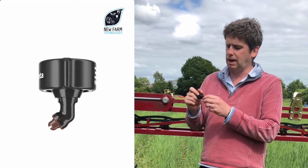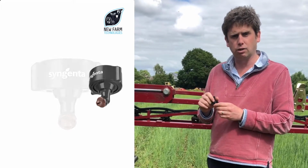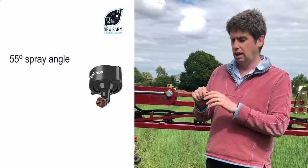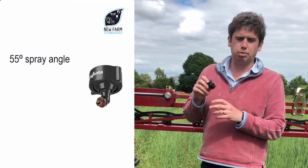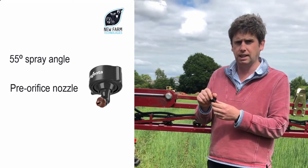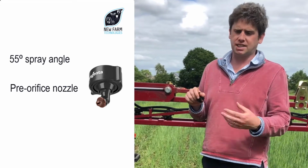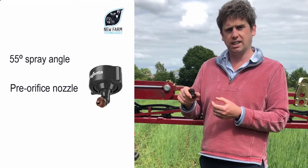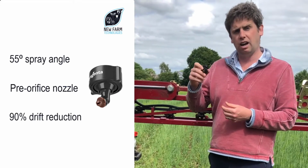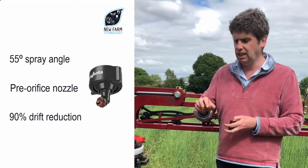And what's key about the 3D90 is several things. A, it's got a 55-degree angle, so that mitigates the clods and shadowing we see. B, it is a pre-orifice nozzle, so it gets its drift reduction capability and is pulse width modulation compatible. And C, which is the most important, is its 90% drift reduction. And that is really important because we can get good deposition of product without compromising efficacy.